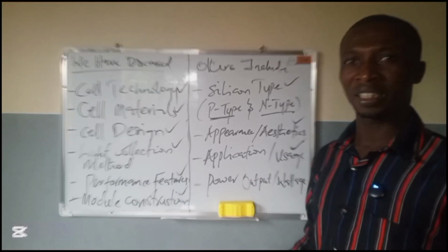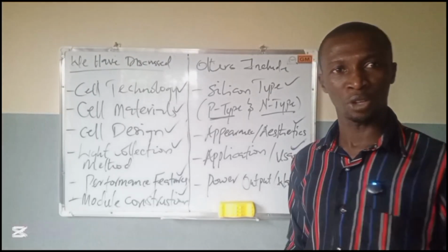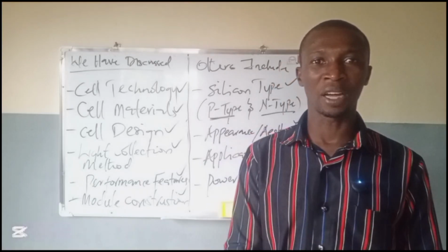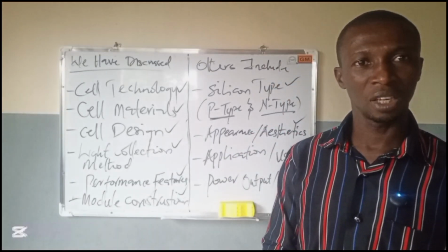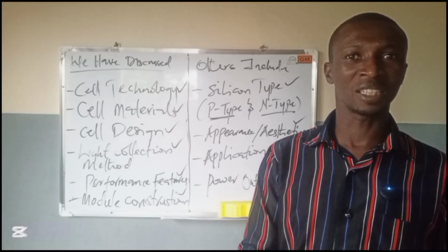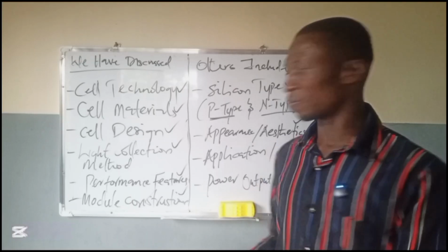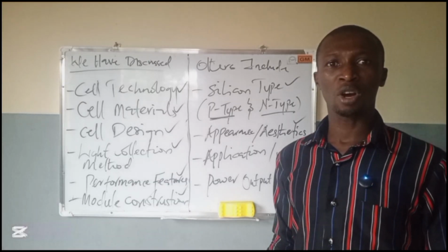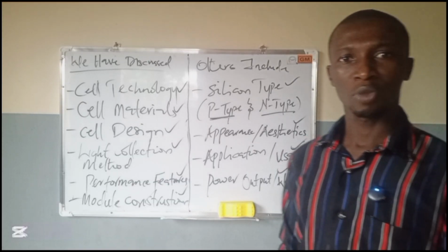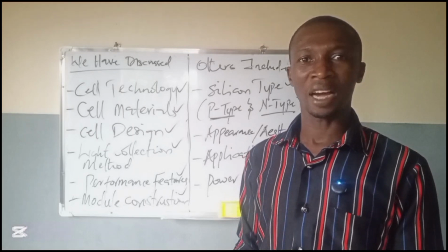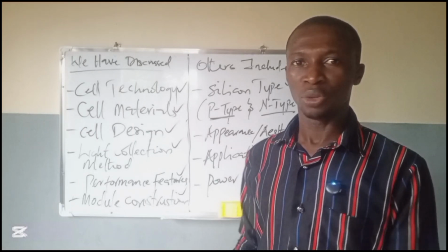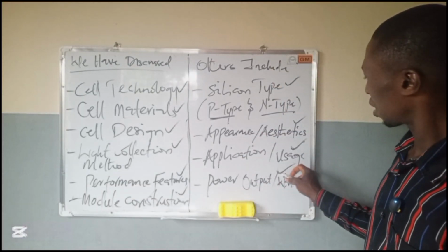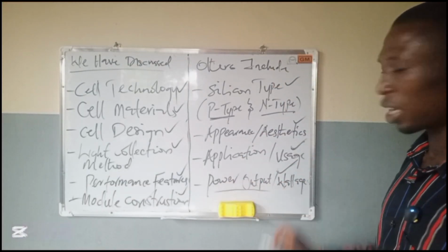There are panels that are not suitable for a PWM charge controller if you're using a 12 volt battery. It is usually ideal to use 12 volt solar panels rather than 24 volt solar panels. So there are panels that find themselves being applied wrongly. So we'll also talk about power output. A manufacturer of a solar system or a solar generator can rate the panel at 400 watts. You don't go and install a 600 watt solar panel. So based on application, you can also classify solar panels based on their power outputs.